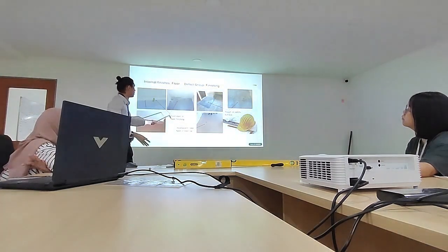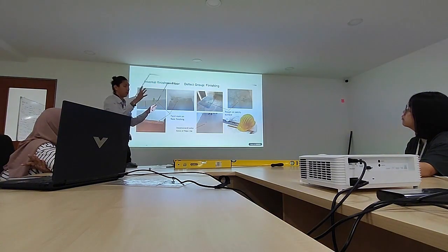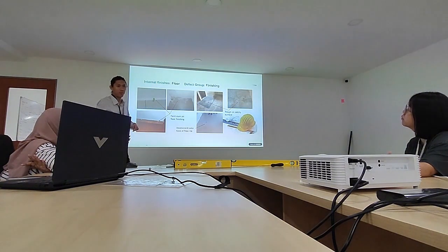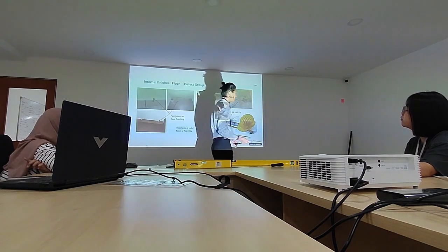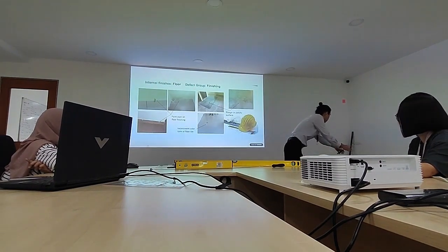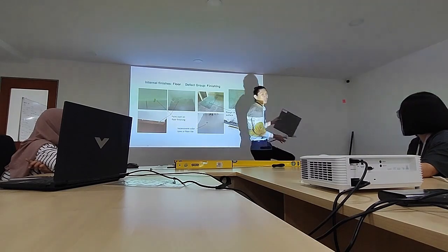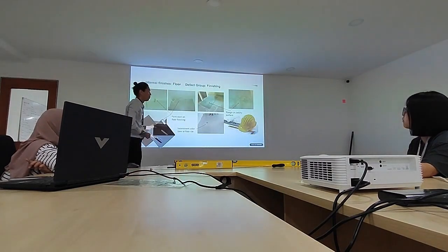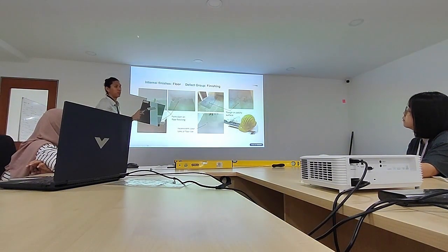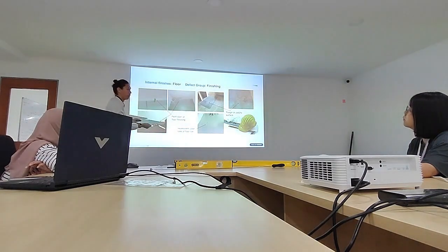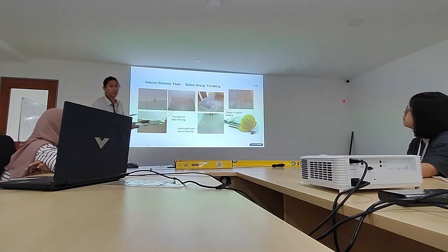So on site, it is very important to differentiate the tile batch. This is the tile code. But on my side, we not only see the tile code, we also see the batch. This house on site is which batch. Then you have to separate the batches: this is batch 1, batch 2, this is batch 3.